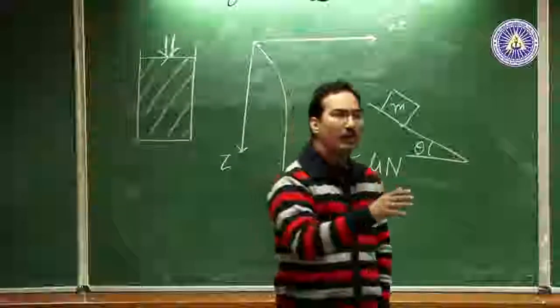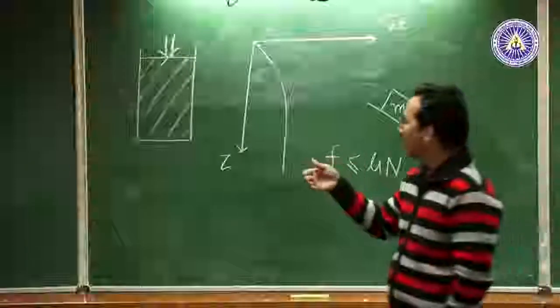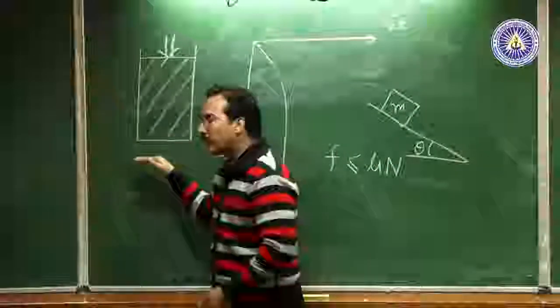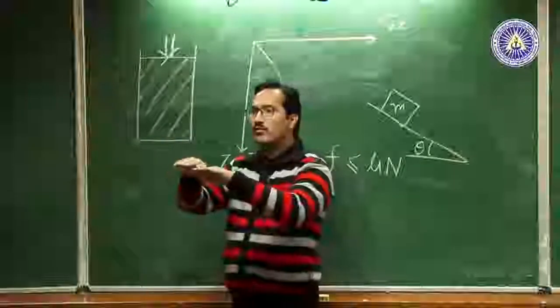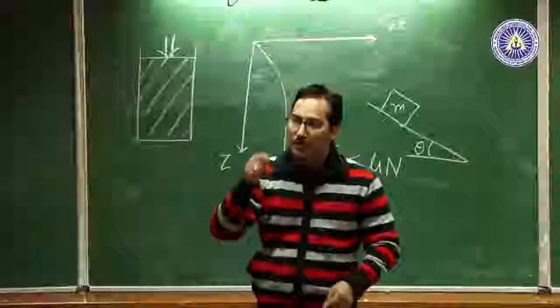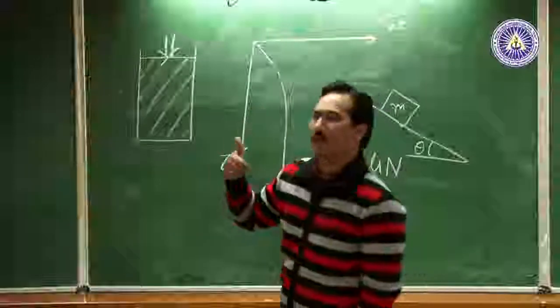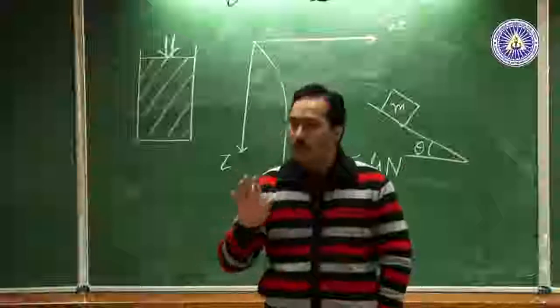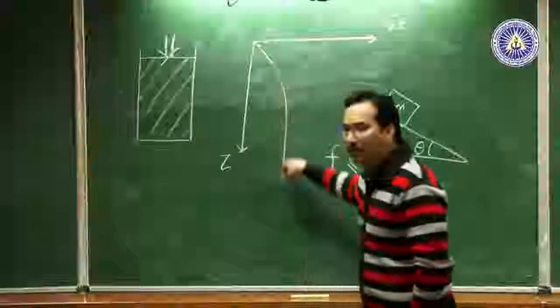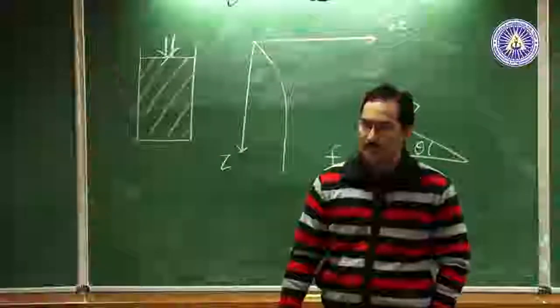So if you really want a good match with the simulation or experimental data, what is typically done in the experimental protocol is that you fill the container with a plate and then you move the base plate slightly, so that you ensure that the particles are indeed sliding at the wall and the friction is fully mobilized. If you are not doing that, you may not get the data fitting the curve that you are predicting. All right.